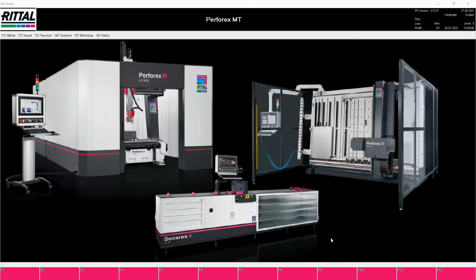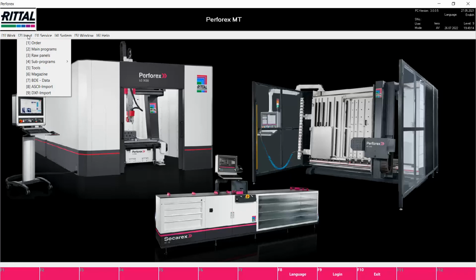To make a main program, we're always going to start with the input dropdown. Up at the top of the screen, if I click on number 2, input, I can come down to main programs. Now we're assuming that everything has already been created. Our tools are set up, our component parts and combined parts, everything is set up, and all we have to do is land them on a panel. All right, so I click on main programs.